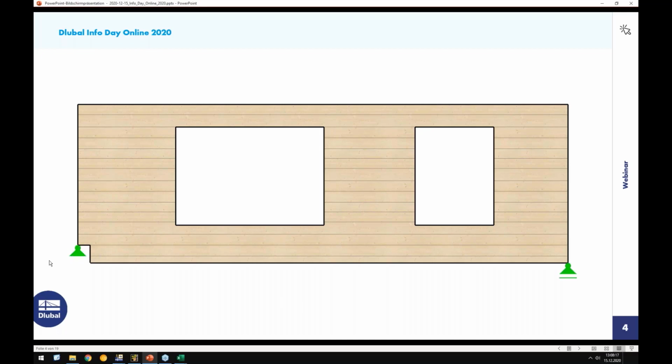Okay, so the next thing is, of course, we need to take care about the supports. In this case, it's just, for demonstration reasons, a nodal support. We will not use it afterwards in our design, but for the slide, it is okay. Okay, we need to take care of the FE mesh. So what size should be used or is suitable?